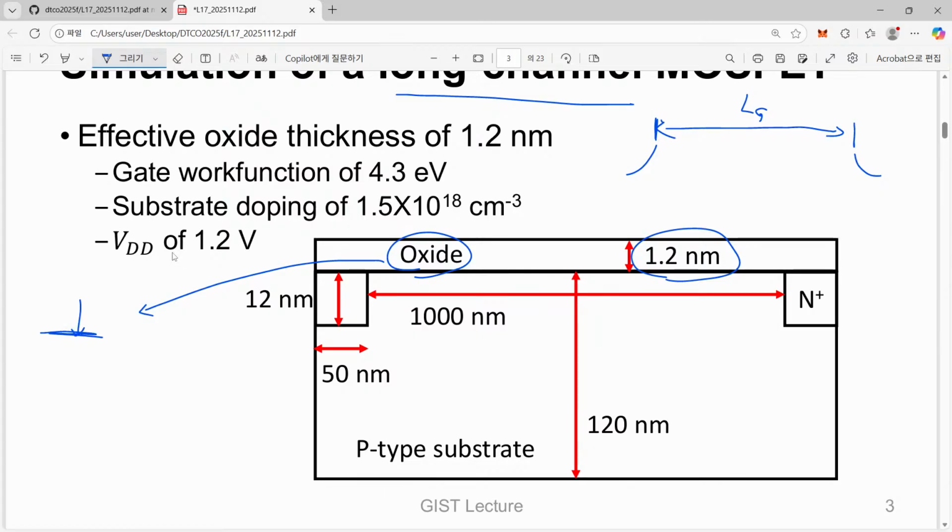purely silicon dioxide oxide. Below this level, if we reduce the oxide thickness even further, then we cannot make a successful MOSFET, because in that case we can have a really high gate current. The gate should be an isolated terminal, but if we have too thin an oxide, then we can have current conduction through this very thin oxide layer. So this is one limiting value for our oxide layer.